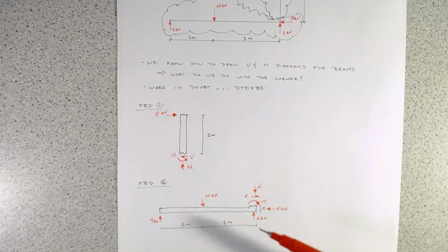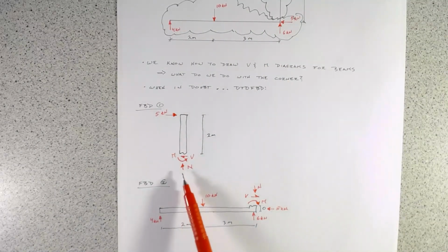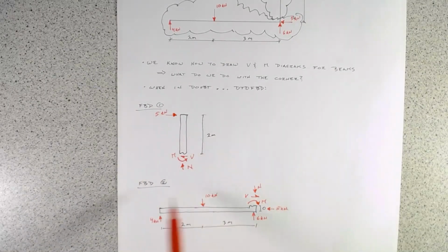So if you have an element on one side of the cut, the magnitude of that element will be the same, but the direction will be opposite. So it's really clear to see with the axial load here and with the shears, same with the moment. We're going counterclockwise on the top, and we're going clockwise on the bottom. And the last thing to note is that if we have guessed wrong here, that's fine. We'll flip it, and that means that it flips on this side too. So now all we have to do is apply our equations of equilibrium, and then we'll know what the magnitude of these moments or these shears are in the element.